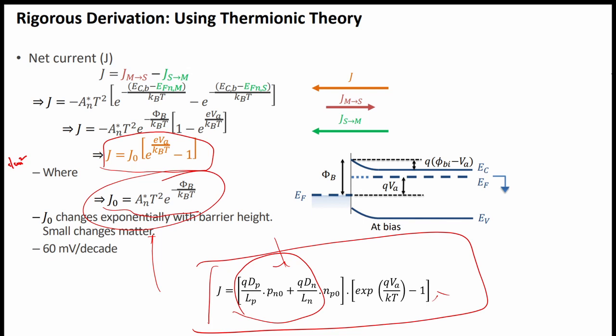If the leakage current is more, even when we are not using our cell phone, it is still consuming energy, which is not required, and our battery is dying out. So that's why this leakage current is very important.